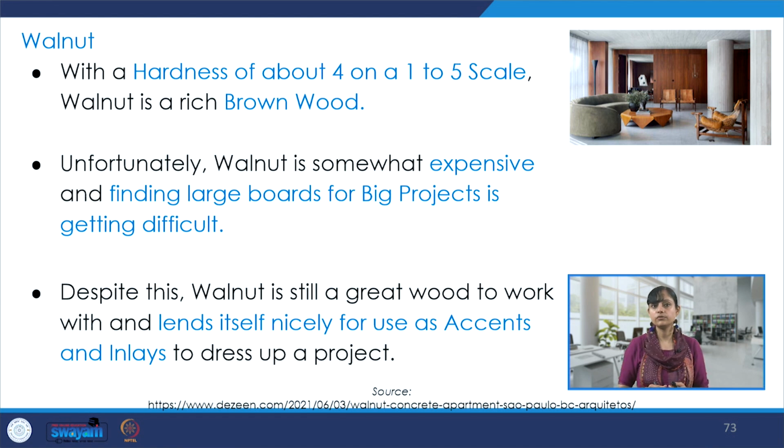Then walnut, it's one of the hardest woods. If I have to talk about hardness on a scale of 1 to 5, walnut is somewhere around 4. So very hard, rich brown color, and it's expensive. It's difficult to find large boards of walnut for big projects. So all these things have to be thought about before selecting this. Despite this, walnut is still a great wood to work with and lends itself nicely for use as accents and inlays. So very interesting and intricate details can be achieved in this, and for that skills are required, and not everybody can work with walnut.